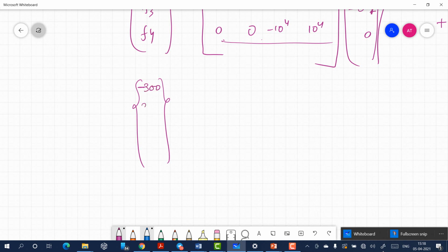And then on node number 2 I have 300, but then there will be no displacement. So let us keep it minus 200. Minus 200, 300, minus 125, and on D4 I will have a reaction force in the positive direction, let us say 100. Okay, so these are the forces, and then I have this stiffness matrix.